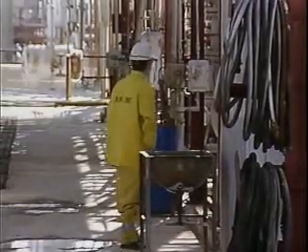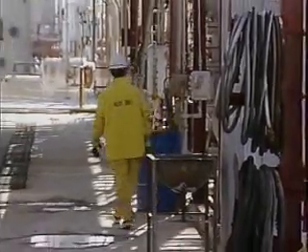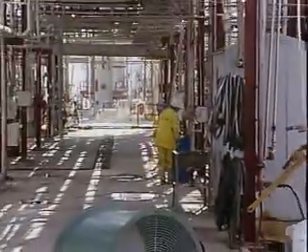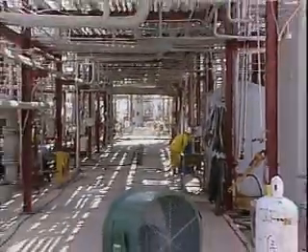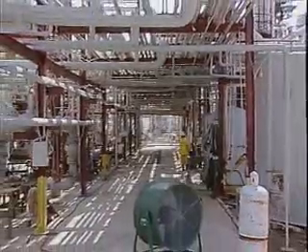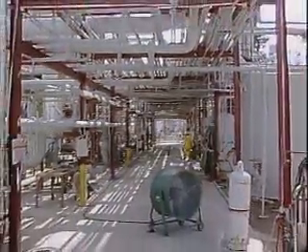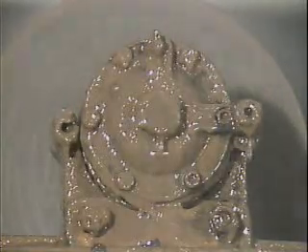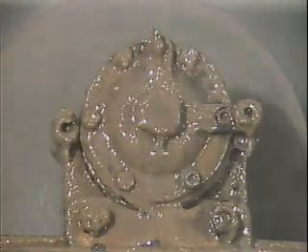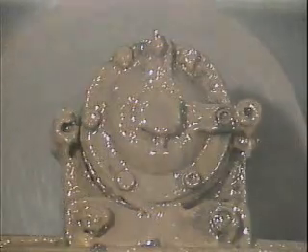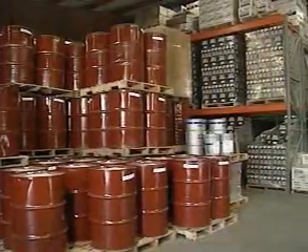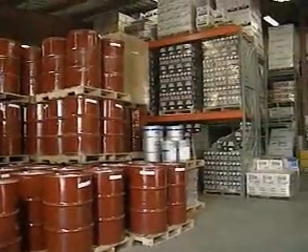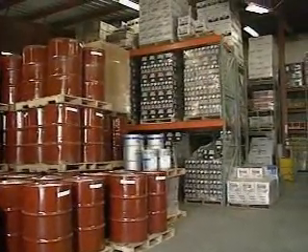Substances or conditions in the environment where a lubricant will be used also affect lubricant performance. For example, a lubricant must be able to withstand chemicals that may tend to break down the lubricant. And if there's water in a system, a lubricant that resists emulsification is usually required. In most cases, lubricants contain additives which also affect lubricant selection.